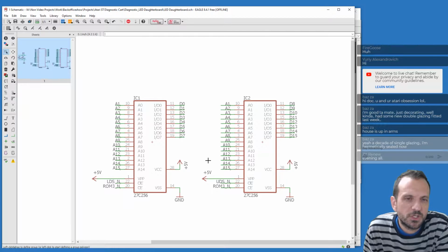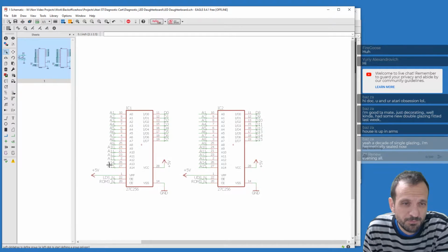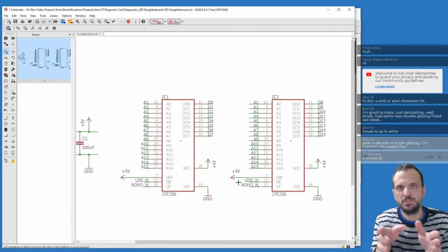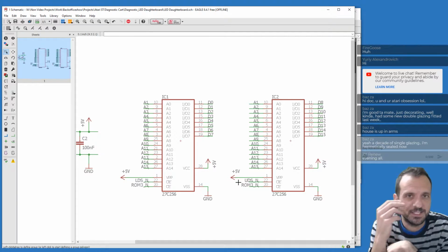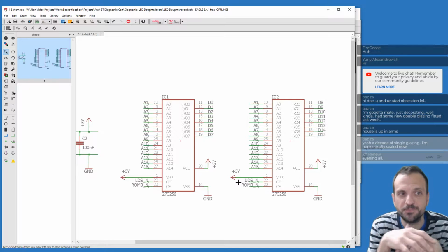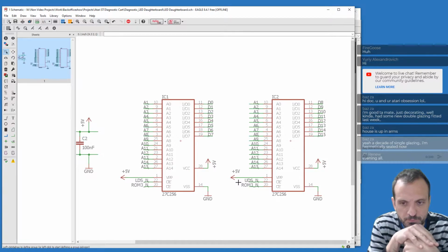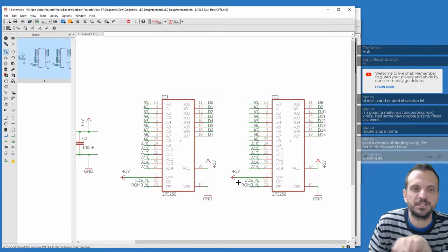Or you could try to put a 7-segment screen, and we could put a controller for a 7-segment display. The downside is, you've seen them in motherboards where they have 2 digits of 7-segment. When this is running, it's going to be going brrr, mega fast. So in general operation, and then when it slows down, we're just going to be manually tweaking address lines and data lines potentially. We'll be able to probably hold them a bit longer. So I don't think the 7-segment's going to work.